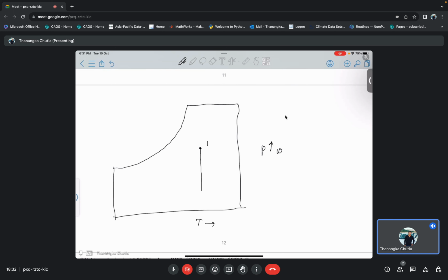If I draw a vertical line from here, this is basically my T dry bulb temperature. Now keeping the pressure constant, if I go horizontally and strike at RH equal to 100%, because if relative humidity is 100% then it is completely saturated, this particular temperature will become my T dew point temperature. Now if you want to go adiabatically, it will be a sloped line. The constant adiabatic lines are there, and if you strike at this one point, this is basically my T wet bulb temperature.